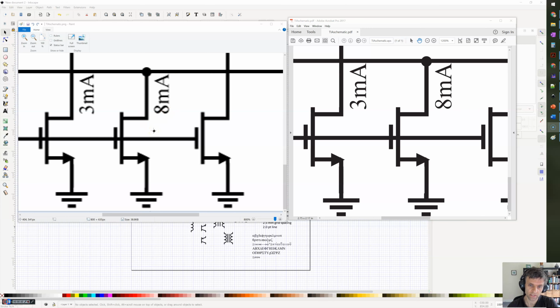Another problem you have is because these file formats are defined pixel by pixel, the file size would get huge if you define them at a fine enough resolution that they'll look good. To prevent the file size from getting huge, usually some compression is applied, and so then with lines and text, you start seeing these sort of gray, blurry artifacts around the edges of them, depending on the amount of compression applied. So generally, these are not good file formats to use for line drawings and drawings of text.